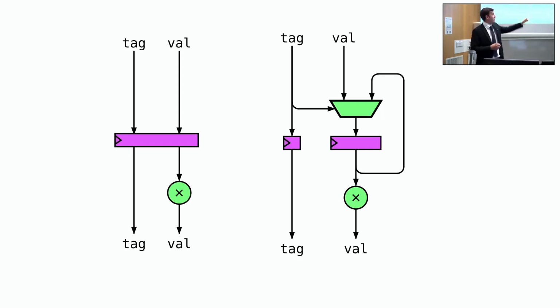Of course, this multiplexer will have some cost, but in practice, synthesis tools in ASICs will convert this to a clock gate for the registers, and in FPGAs, this will become a clock-enable signal. So while we generate this code, the synthesis tool will then change it to a more efficient version.